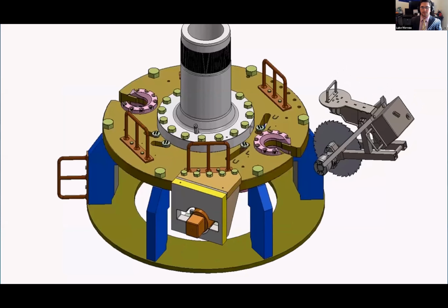Next up, we did a motor torque calculation, which we found to be 36 foot-pounds. We used the pressure gauge to find the pressure in that calculation. Next, we did a motor RPM calculation, which we found to be 385 RPMs. Through the research that we did, we found that cutting Inconel, your RPM should be low, which we found to be below 450.